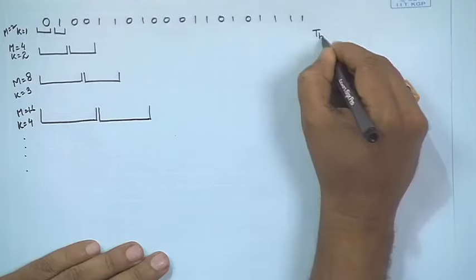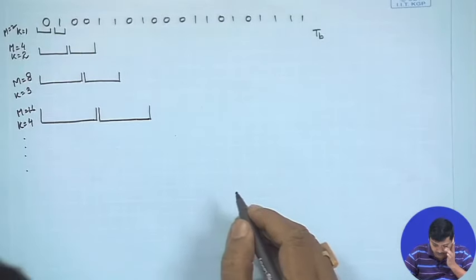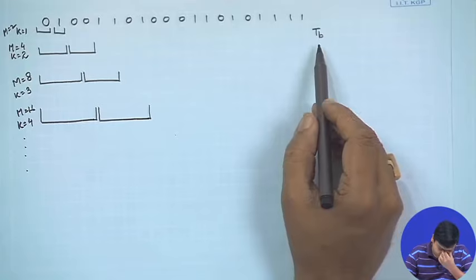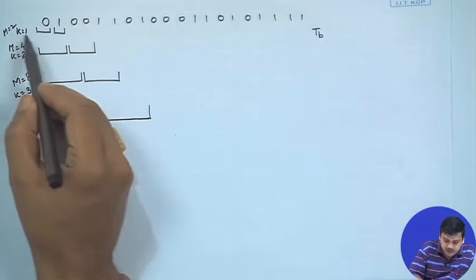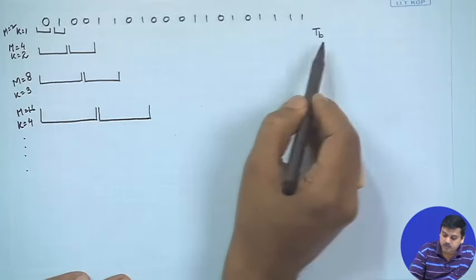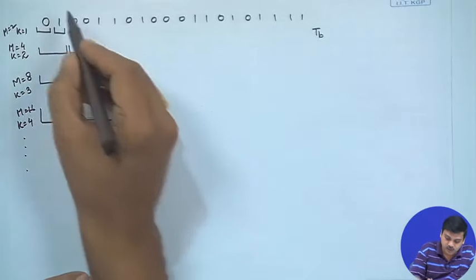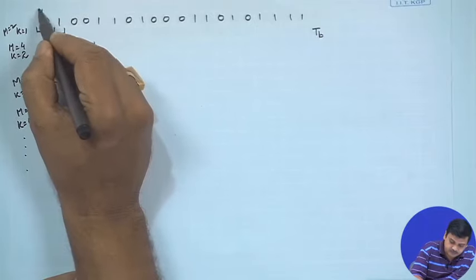One, where we compare that if I have a certain fixed bit rate, with bit duration TB, that we have to use. If k equals 1, our symbol duration should be equal to TB. So, this is TB, let us say.